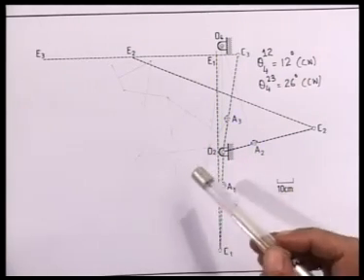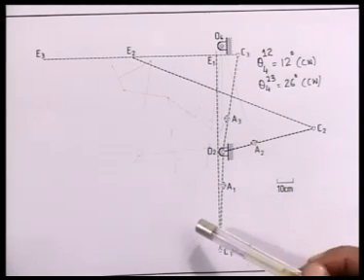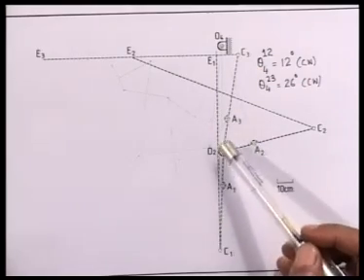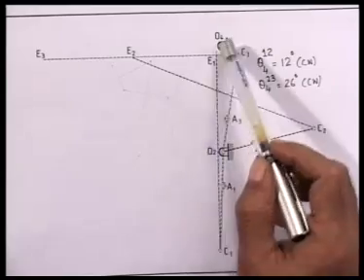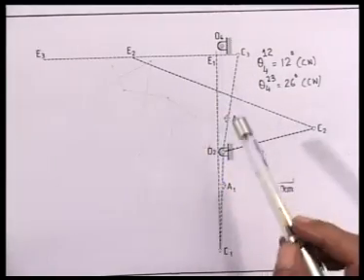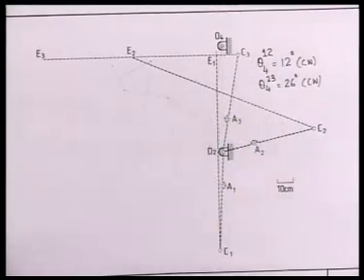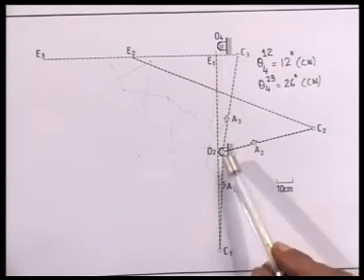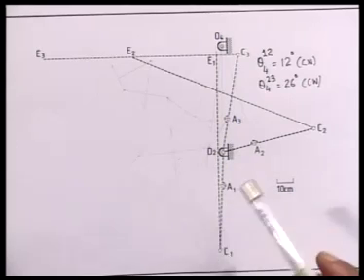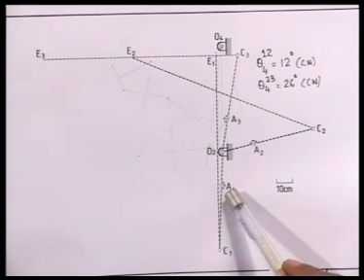We achieve this design in 2 stages. First, we design the 4-link part of this mechanism, namely O2, A, B, O4. To obtain this 4-link mechanism, we conveniently choose the location of A, the hinge on link 2. A1 is chosen arbitrarily.